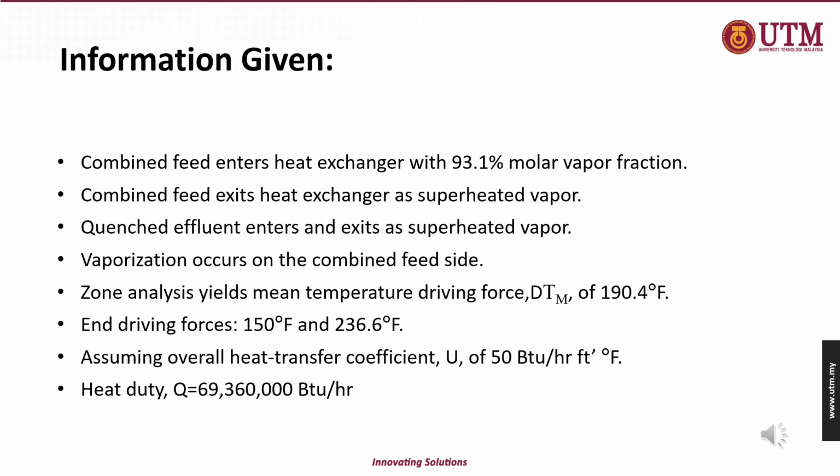Zone analysis yields mean temperature driving force, delta Tm, of 190.4 degrees Fahrenheit, and driving forces of 150 degrees Fahrenheit and 236.6 degrees Fahrenheit. Assuming overall heat transfer coefficient U of 50 BTU per hour square feet degree Fahrenheit,